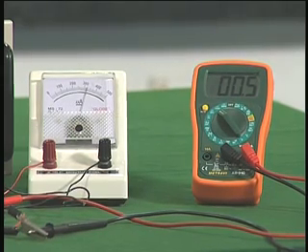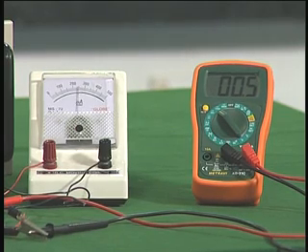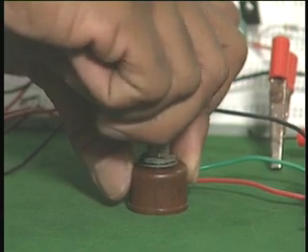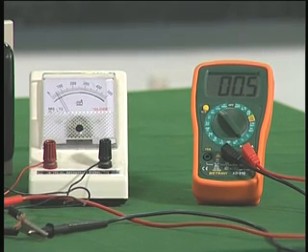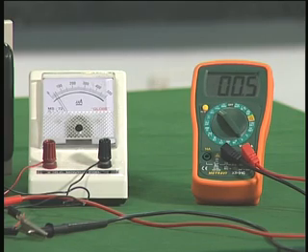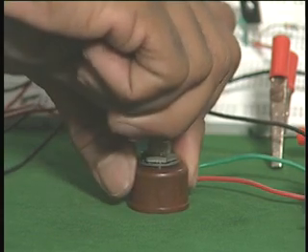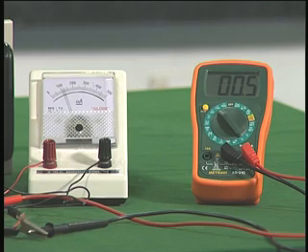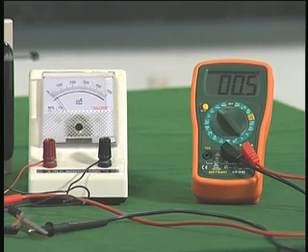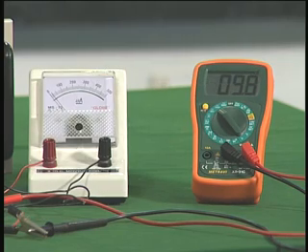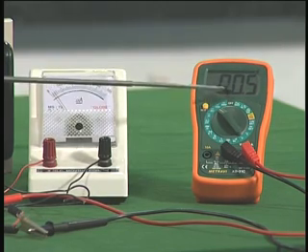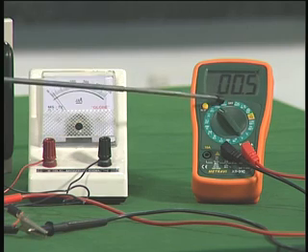Now I am going to reduce the gate current, keep observing only here. Now see what happens. I reduce the gate current. So I have reduced the gate current to a very low value, as you can see here, almost 0, and still this is conducting, it is still only 0.5 volts, that means the SCR is still conducting, right.